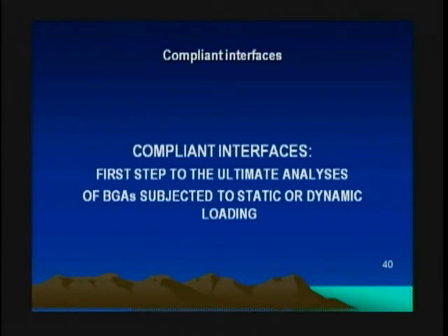This, by the way, is relevant to everyone who works in the field of three-dimensional packaging, including so-called TSVs, through silicon vias. And one of the ways to bring down the stresses in TSVs is to employ compliant attachments between the copper and the silicon. Well-known approach.